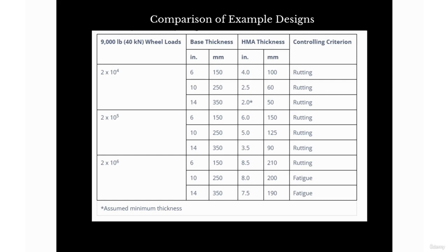That also depends on whether aggregate is available where you are. For example, in New Zealand, where I am on the East Coast, in Gisborne, there was a time when aggregate was really hard to come by because of the cyclones that washed away a lot of bridges. So there was no aggregate, and maybe it'll take a few years to fix the bridges. You would then rather spend your money on the asphalt. Then maybe you would try and balance it out.